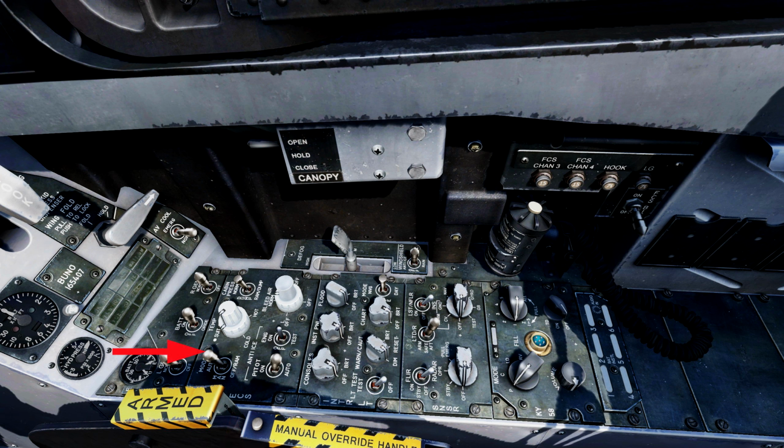This consists of a mode switch that controls the general airflow into the cabin, but generally this is always set into the auto position. Next to it is your temperature control dial and a cabin pressure dump switch. The pitot switch can be set to on or auto, and when in auto mode it will automatically come on once the aircraft is airborne. Next to that you have your anti-ice engine control, and next to that you have your bleed air control that siphons air from the engines.